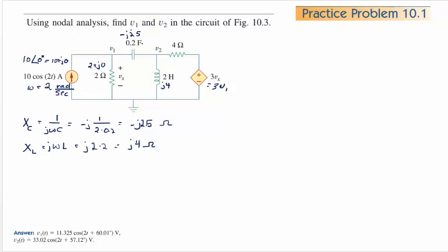So you go through and you take the circuit and you just replace all of the components with their imaginary or real numbers so that everything is expressed in ohms in this circuit. And then after that we solve the circuit using techniques that we already know. And we're supposed to use nodal analysis on this circuit. So nodal analysis is applying Kirchhoff's current law at the nodes in the circuit. I have node 1 and node 2. So at node V1, apply KCL.